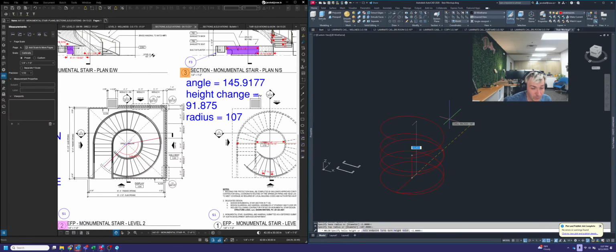So in order to get that to be the correct number of turns, or the correct slope going up here, we need to tell AutoCAD how many turns it's going to make. So down at the bottom, you'll see in the Helix command there are a few different options here. The one that's second back there is called turns. We'll click on that. And right now it's set by default to 3. So how you determine the number of turns that you have to type into AutoCAD is driven by the angle that you're going around this circle.